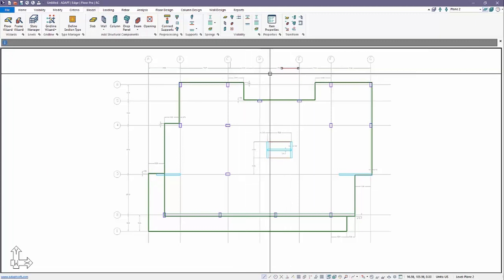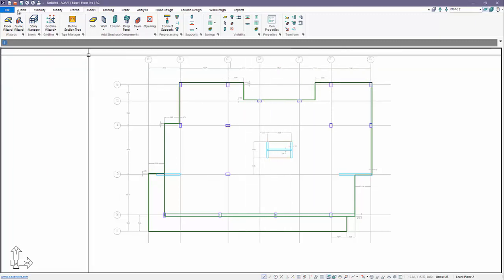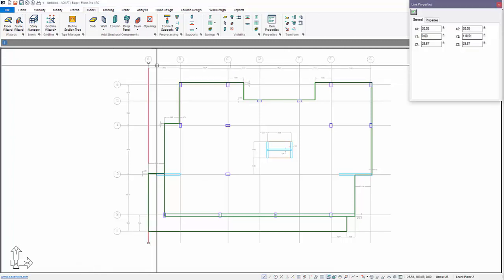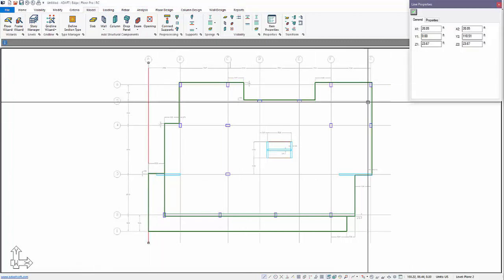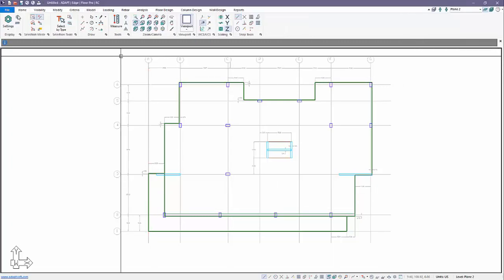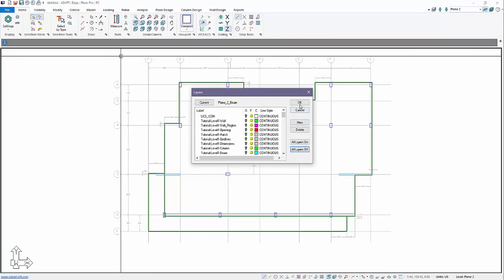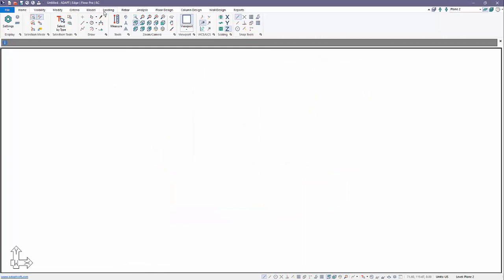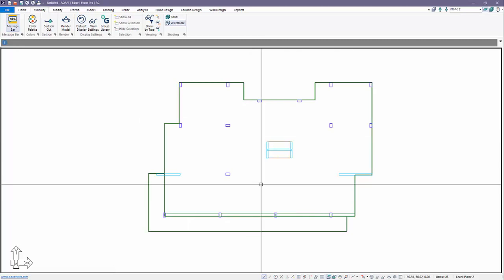This particular grid file can be left on only through filtering layer. So you could technically leave this layer on, turn everything off, leave this grid layer on using the grid lines layer. We'll turn everything off again, and then I'll just reset my structural view from visibility. We'll go back to the default display.